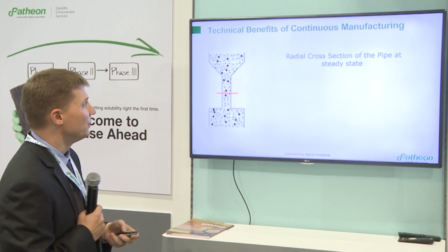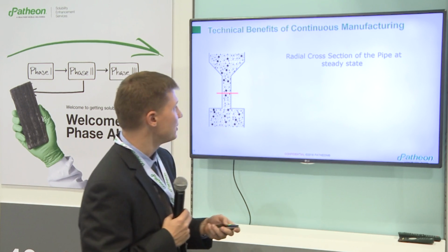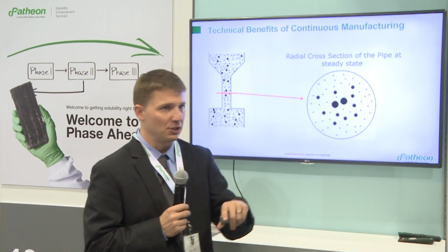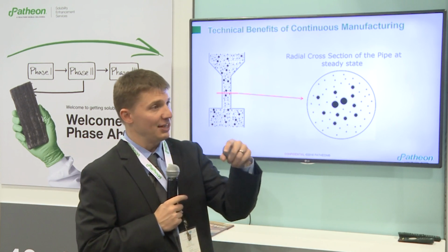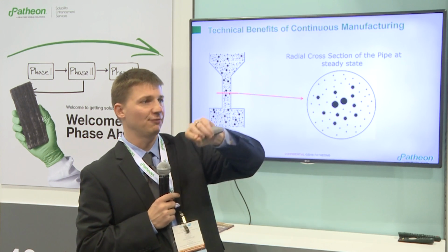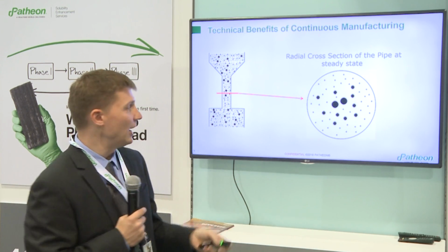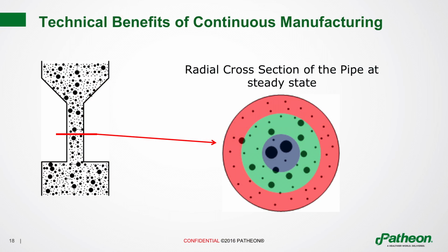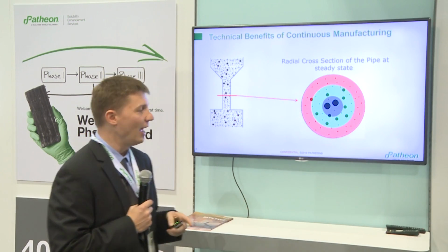That doesn't mean that segregation isn't happening. It actually very much is. And we've seen this in a couple studies, at least the hints of this, where just like anybody who's ever cracked open a Guinness and poured it, you see on the outside of a Guinness, you see bubbles going down, which is a really strange thing. That's because on the inside in the middle, there's big bubbles coming up. The small bubbles getting trained, they get taken by the fast flow and pulled back down around by the water, and so you only see the small ones. Same things happen in these pipes, and you can have something like large particles in the middle, smaller particles on the outside, and smallest on the outside. So it's something we do think about. We worry about it when it comes to sensing and stuff like that, but it doesn't affect your product quality as it's coming out the other end.